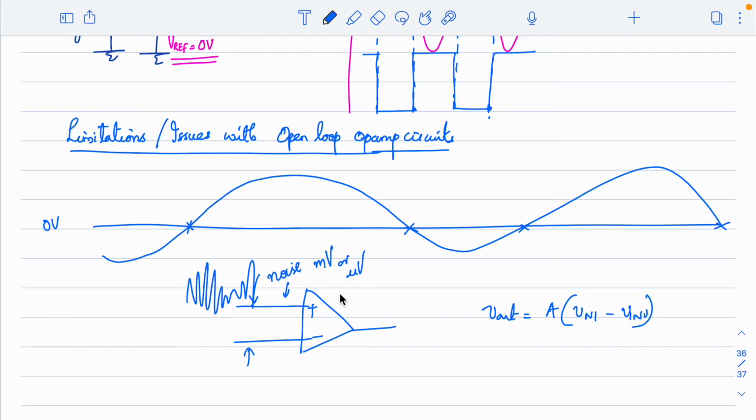Because the noise at the input terminals will cause the output to fluctuate between the two saturation voltages. Noise is quickly varying, while the input signal is very slowly varying, but the Opamp input terminal will not understand that. Based on the signal variation at the input, it will operate and a decision is made.